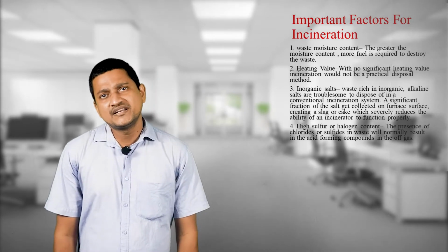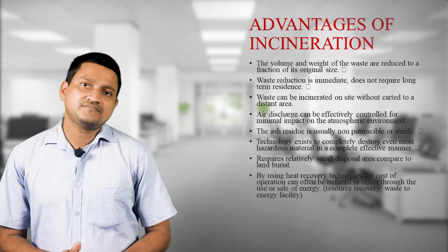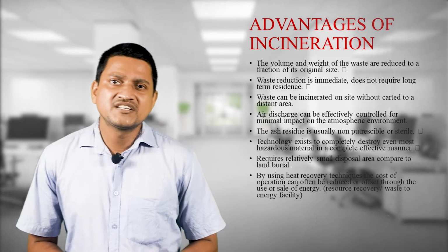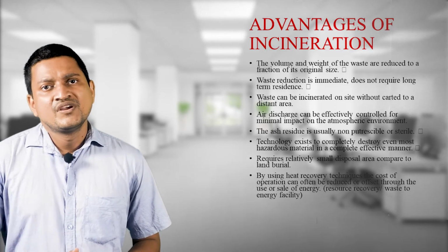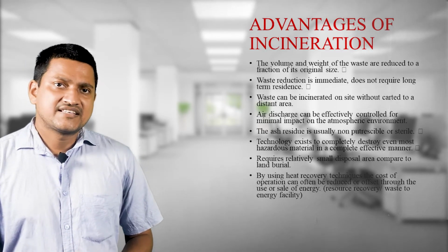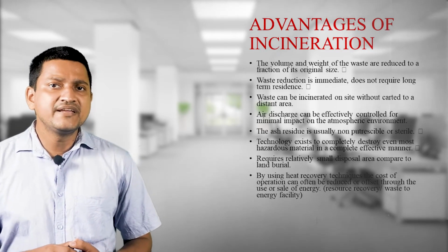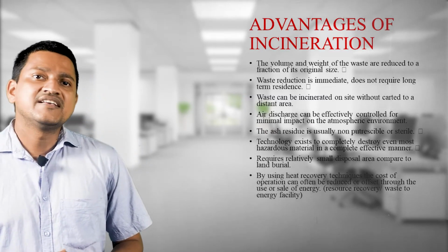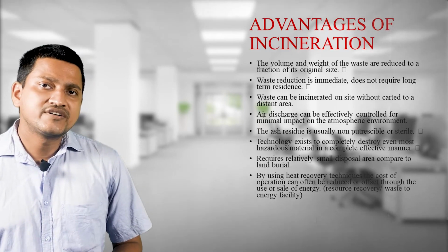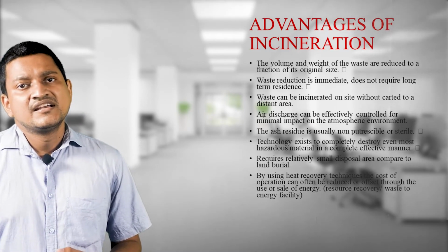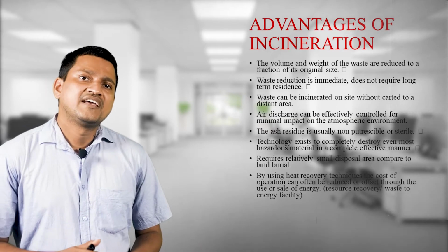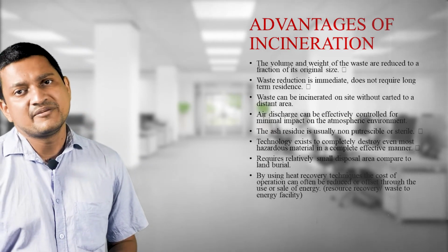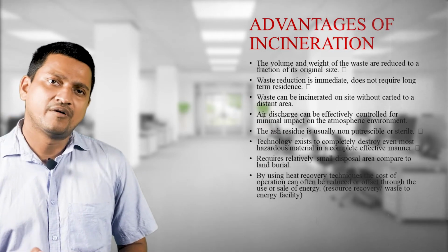Then, what are the advantages of incineration? The main advantage is that the volume and weight of the waste are reduced to a fraction of its original size. Waste reduction is immediate and does not require long-term residence. Waste can be incinerated on site without being carted to a distant area. Air discharge can be effectively controlled for minimal impact on the atmospheric environment.